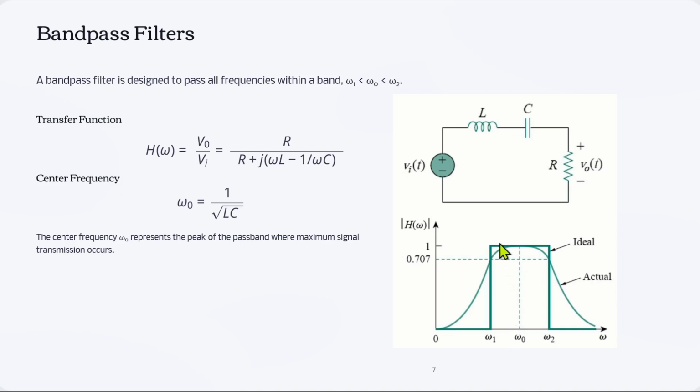If you see, the first half of the cycle represents the high pass filter and the second half represents the low pass filter. At resonance, inductive reactance and capacitive reactance cancel each other, as we know, and only signals near that frequency get amplified at the output. That means it behaves as resistive at this point. So this is the idea behind band pass filters.